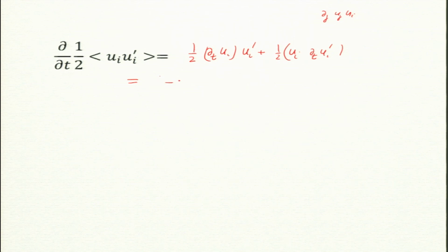I am just going to sketch it. Okay. So, ui prime times uj del_j ui, but this operator del_j will not act on ui prime. So, I can push it inside, because this operator acts only on r position, not on the r plus l position. Now, I am doing averages. So, this average will come here. So, the third order correlation function has come now. Now, that I relate to the third order structure function, by all the derivatives which I have done.